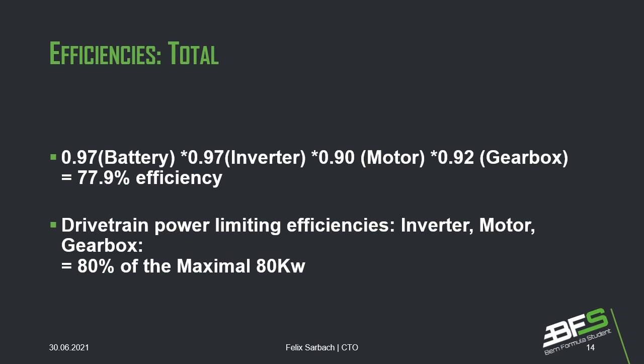Adding all efficiencies together, we can estimate 97% for the battery, the same for the inverter, 90% efficiency of the motor, and 92% in the gearbox. That gives us a total efficiency of 77.9%.